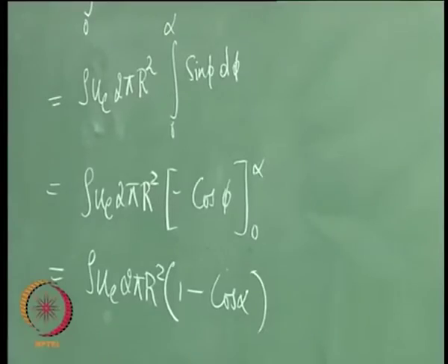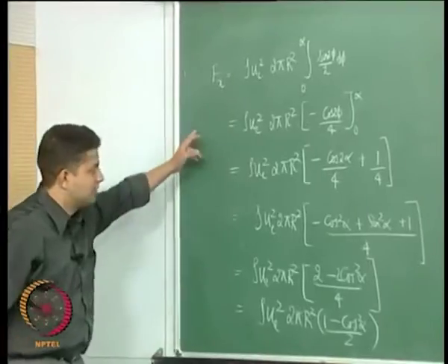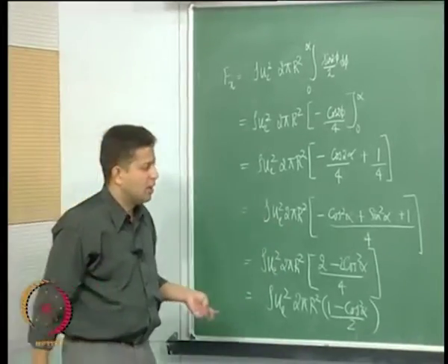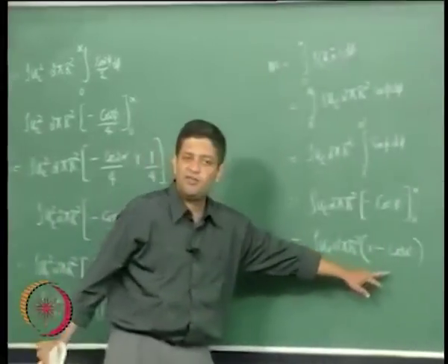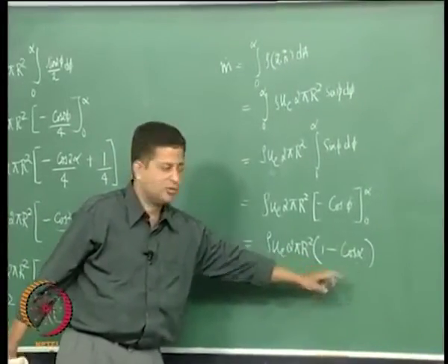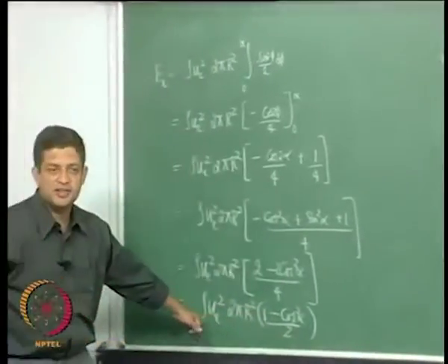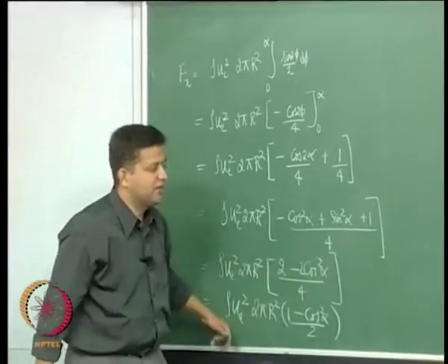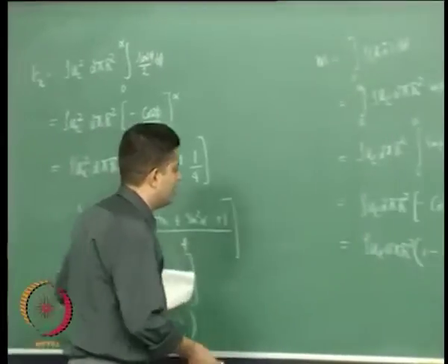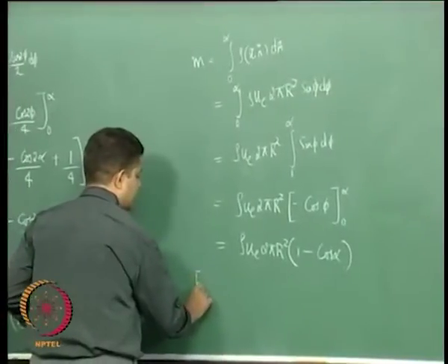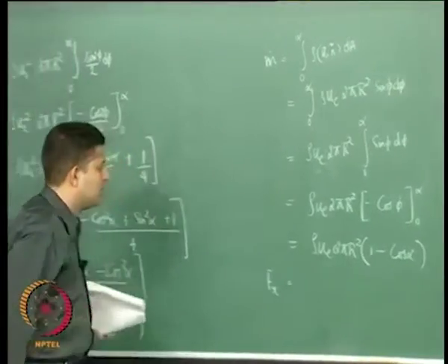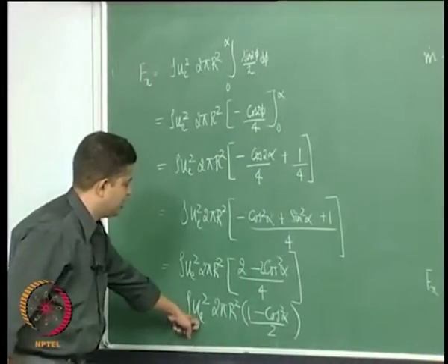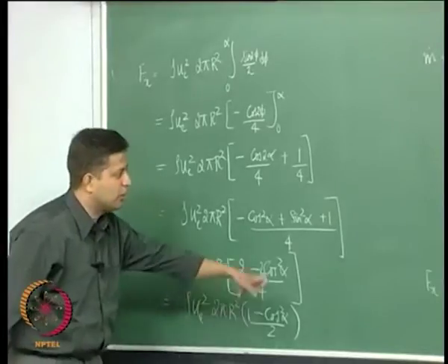Okay. So, we have got two terms here, one is the thrust and one is the mass flow rate. Mass flow rate, if you can see, I have put it as a function of cos alpha, which is why I wanted to retain this in terms of cos. Now, if you look at this, I can club these two and write my thrust in the x direction as F x is equal to, you will have a u e term and 2 pi r square will go away.